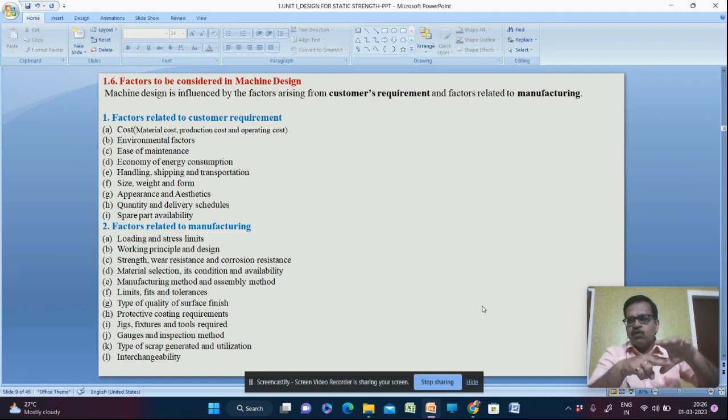The bearing hole with its minimum size should always be greater than the maximum size of the shaft. Then only there will be relative motion between the bearing and the shaft. So that is the main reason for having the limits when we manufacture the things.